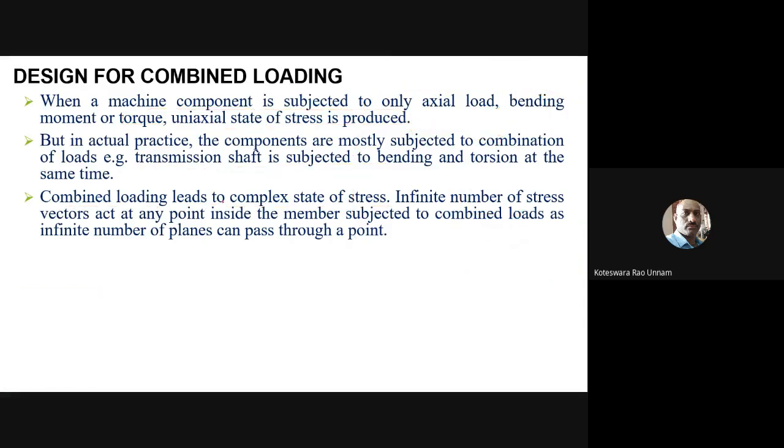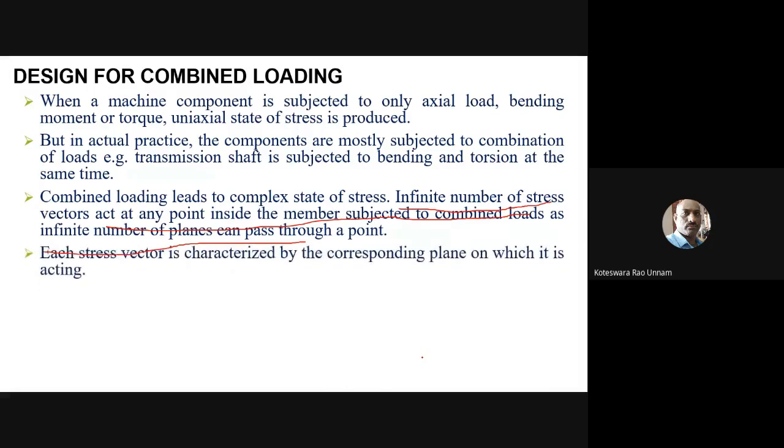So now when we have a complex state of stress, an infinite number of stress vectors act at any point inside the member subjected to the combined loads, as an infinite number of waves can pass through a given point. So that means you can define an infinite number of states of stress at a given point because of this complex loading. Each stress vector is characterized by the corresponding plane on which it is acting.